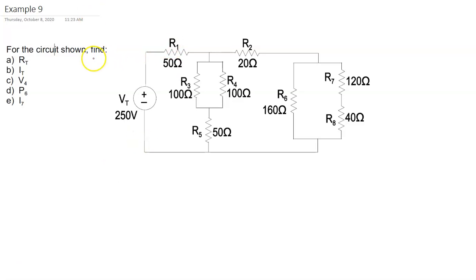And now what we want to do is start off by again identifying series and parallel relationships. With the source here, as usual on the left, very often it's the right we'll start with. Okay, so let's think about series and parallel relationships over here. This branch containing R6 is in parallel with this branch containing 7 and 8. Before we can tackle that one, we should think about the fact that 7 and 8 are in series over here. Okay, so we'll start with 7 and 8 then.